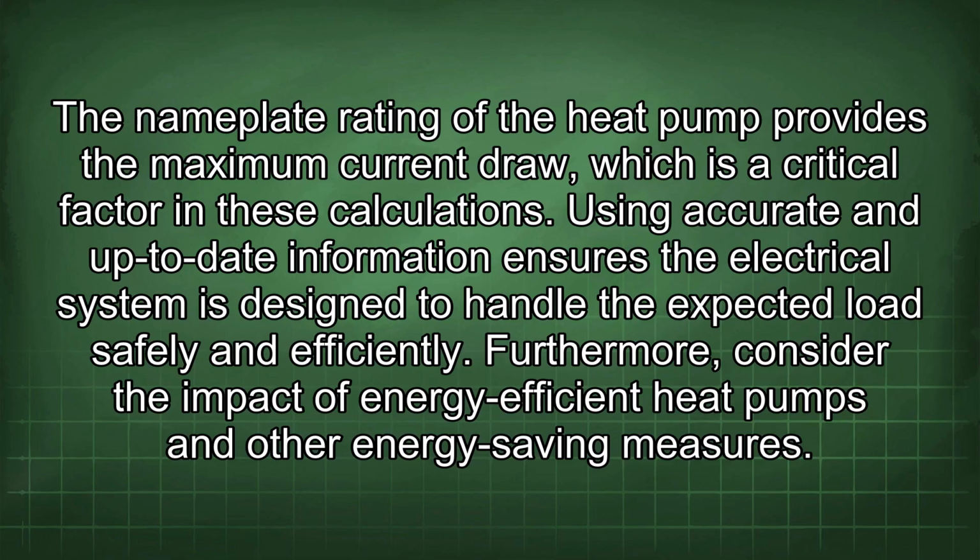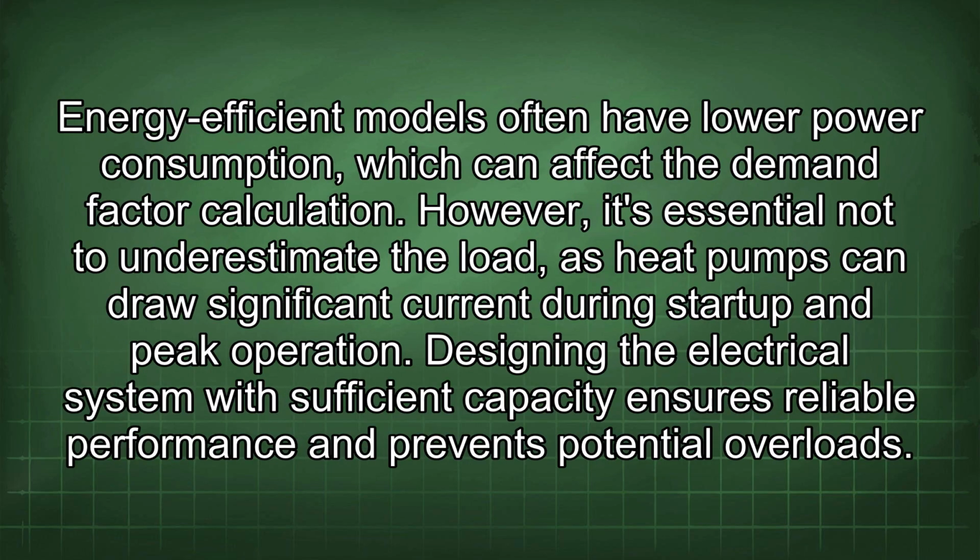Furthermore, consider the impact of energy-efficient heat pumps and other energy-saving measures. Energy-efficient models often have low power consumption, which can affect the demand factor calculation. However, it's essential not to underestimate the load, as heat pumps can draw significant current during startup and peak operation. Designing the electrical system with sufficient capacity ensures reliable performance and prevents potential overloads.